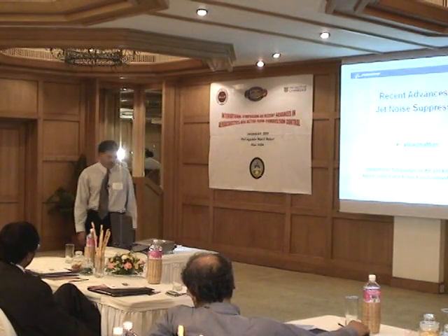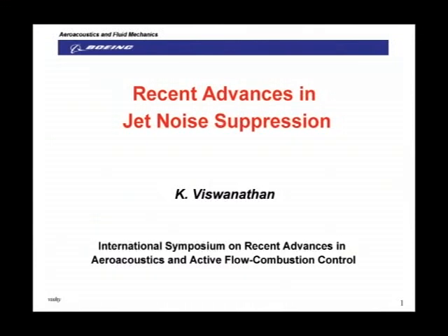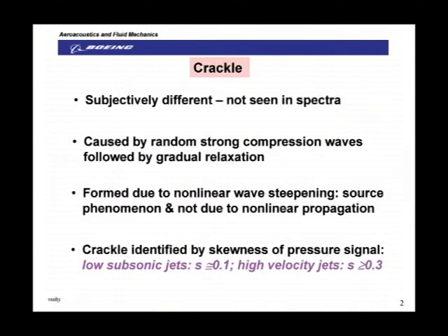3 days. Professor Ffowcs Williams made a systematic study of crackle, which I'm going to address in greater detail here. Now, crackle is a subjectively different phenomenon, a component of noise which is not seen in spectra, which came to the forefront during the development of the Concorde in the early 70s. And this is caused by random strong compression waves followed by gradual relaxation.